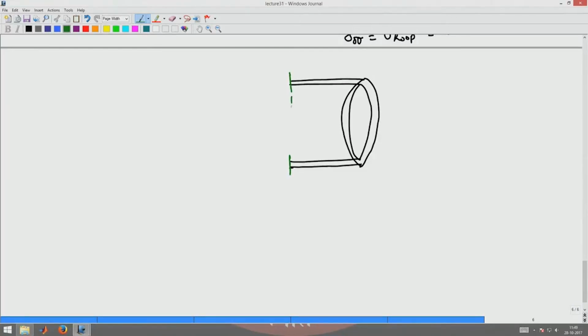That is a cut surface. So, basically I will have these stresses exposed, which is sigma zz, and then I have pressure acting like this on this wall, Pi, and pressure acting like this on this lid, which is also of magnitude Pi.